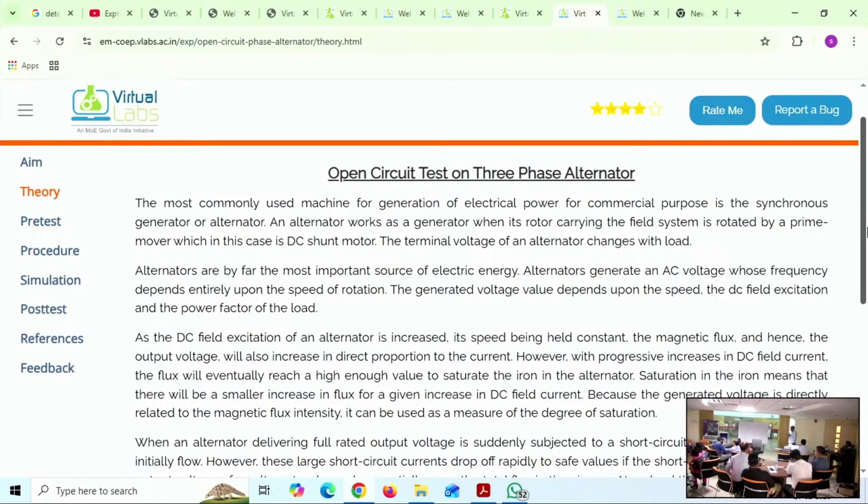Ideally, ammeter resistance should be zero, because it measures current in series and should not take any drop. So its internal, parasitic resistance should be zero. When a voltmeter is connected in parallel, it should not draw any current, so infinite resistance must be there. Practically that is not possible. There may be some least amount of resistance in an ammeter and a very high resistance in a voltmeter. What is the difference?